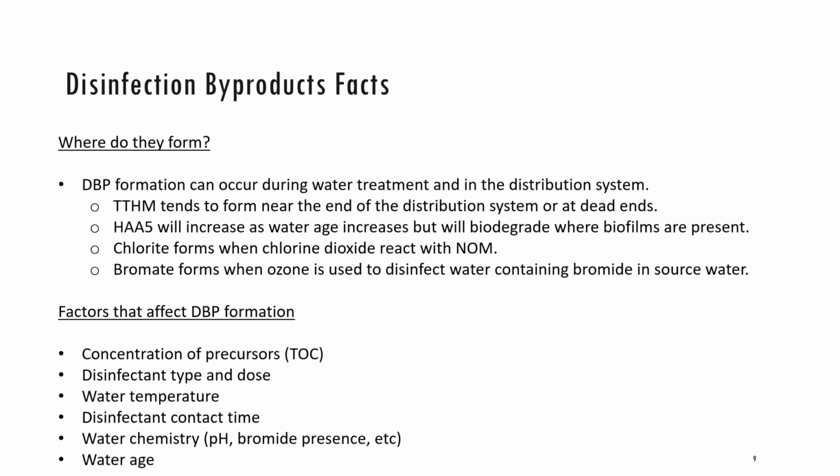HAA5 also prefers to form with increased water age, but HAA5 formation is a little bit more complicated. It favors low disinfectant residuals, which indicates older water, but also favors areas where there is no biological activity, such as biofilms, because studies have shown that biofilms can biodegrade HAA5s.